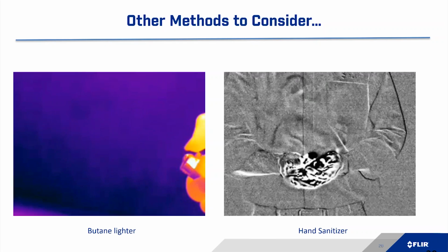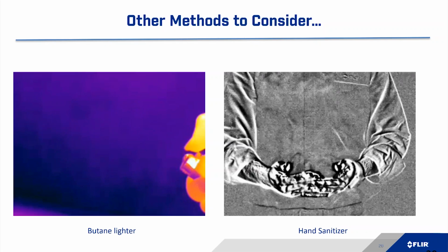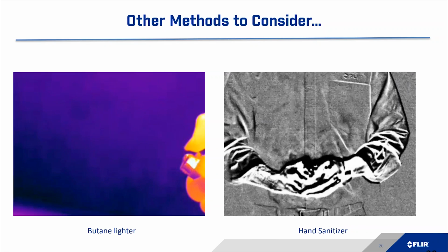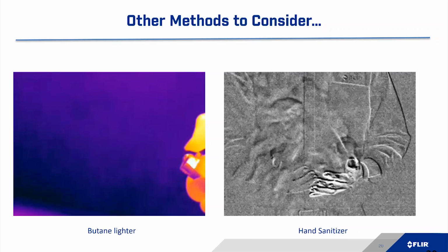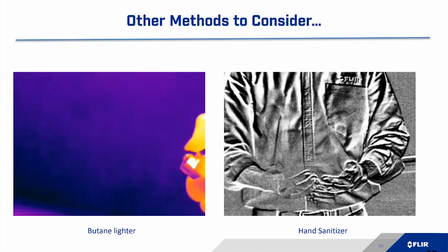And you can see here, when we enter into the high sensitivity mode in the camera, you can actually see the small vapors and emissions from a hydrocarbon perspective coming from the hand sanitizer. So another great way to just do a quick verification that your camera is up to snuff, if you're not going to walk through the 5-part process in the FLIR manual.